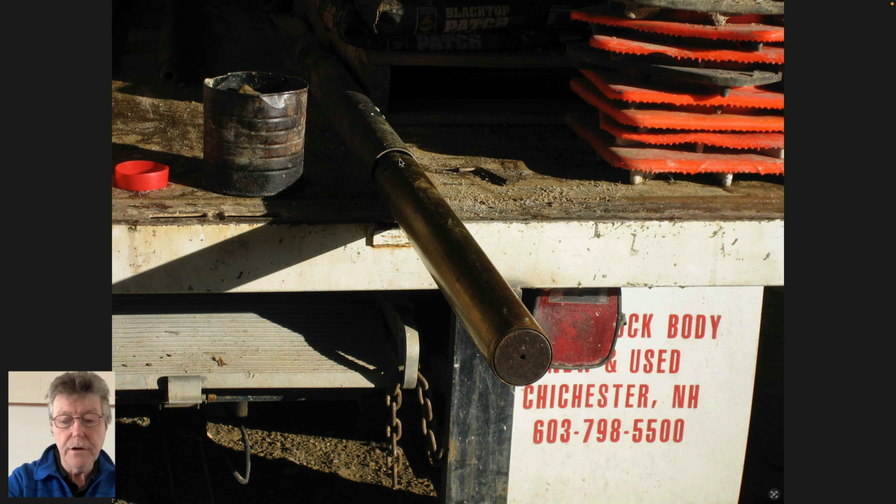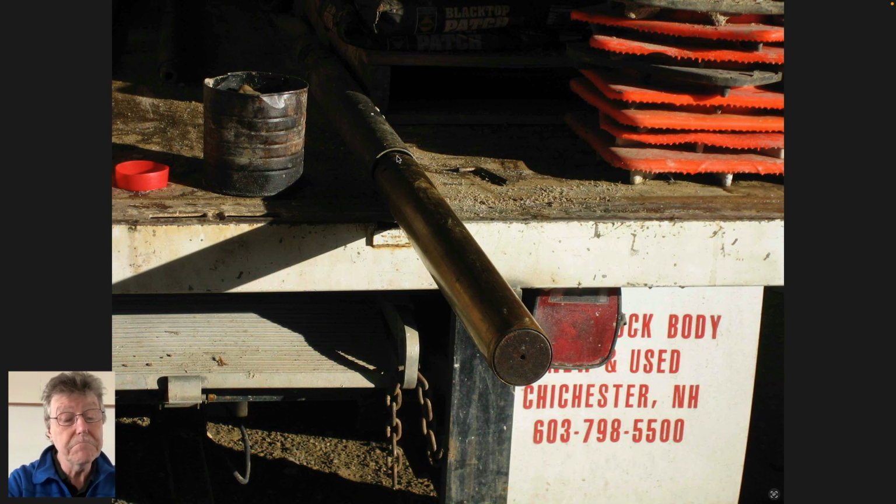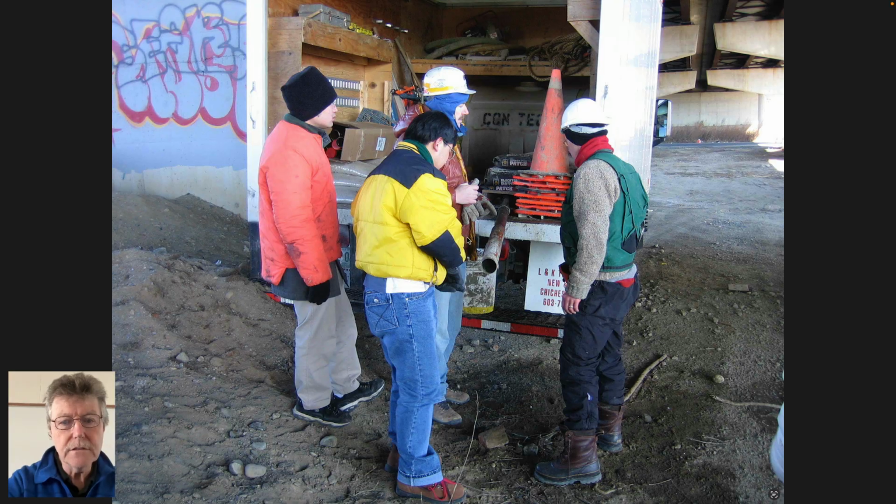And so you attach this tube onto this coupling by unscrewing some bolts using an Allen screw. They're recessed when you take it off. When you slide it on, you unscrew them so they come out into the holes on the top of this assembly here. So that attaches it. You place it on some drill string and put it down to the bottom of the hole. Once it's down there, you press this whole assembly into the bottom of the hole, and you allow this piston to naturally retract up inside as the bottom of the hole goes inside this thin wall sampler. And then once you have that, this is it sampled.